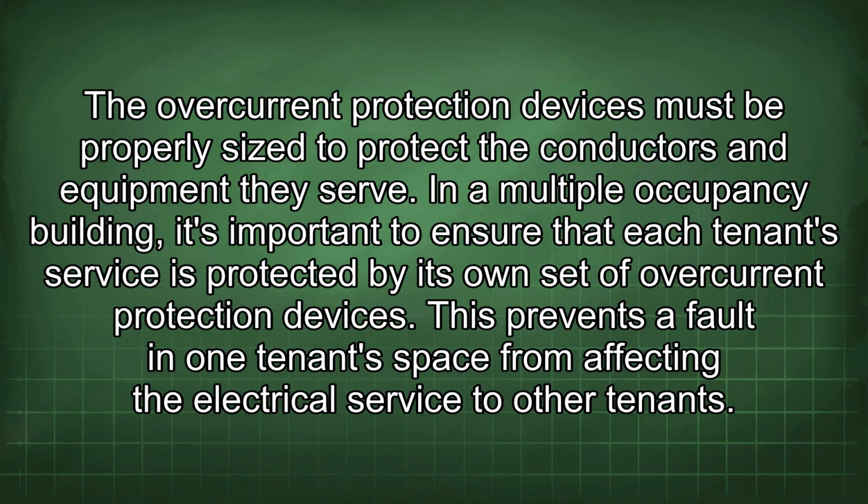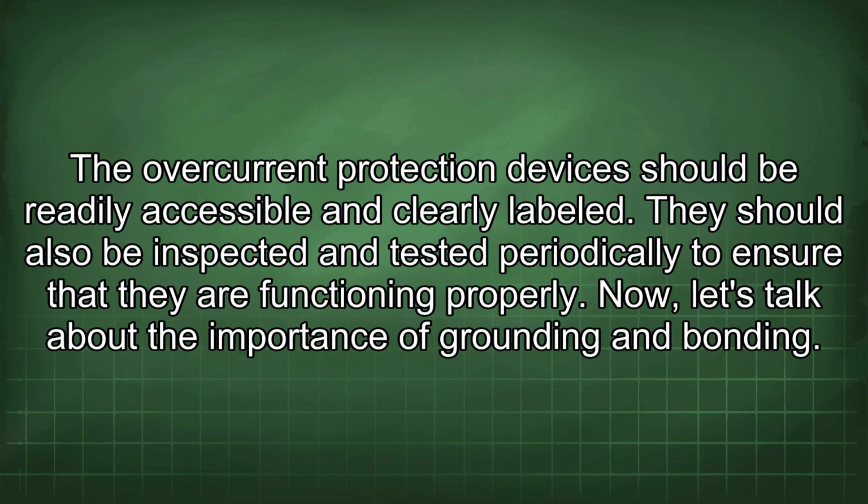overcurrent protection devices. This prevents a fault in one tenant space from affecting the electrical service to other tenants. The overcurrent protection devices should be readily accessible and clearly labeled. They should also be inspected and tested periodically to ensure that they are functioning properly.